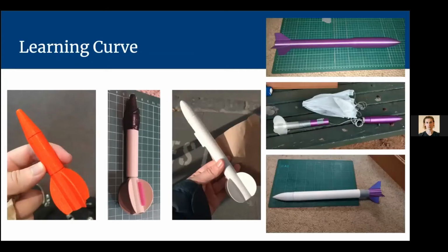Yeah, if you could go back to the little slideshow. And so for that gray one in the middle there, I also learned that if you can see the little nub on the left-hand side there sticking off it, I tried to design the launch lug into the actual 3D printed design, and it turns out that it's better to just stick a bit of drinking straw, chopped.